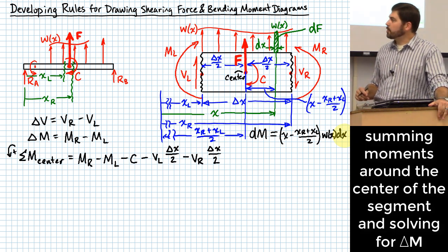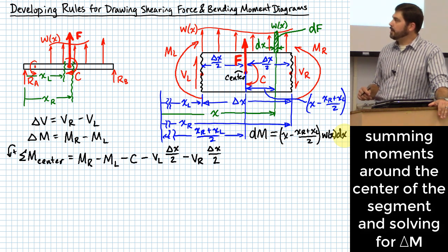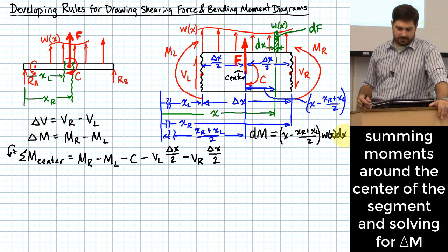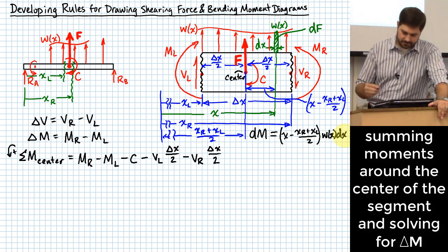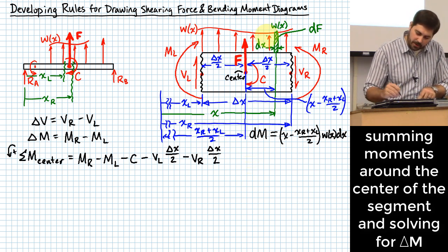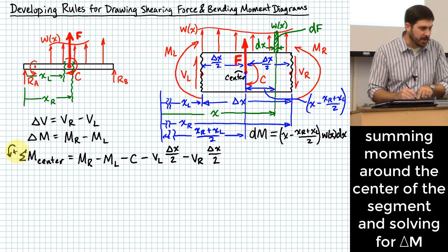So how would I come up with my total amount of moment that would be applied by this whole distributed load? Okay. You might notice I'm counting counterclockwise as being positive, which is the same way I'm counting my sum here.